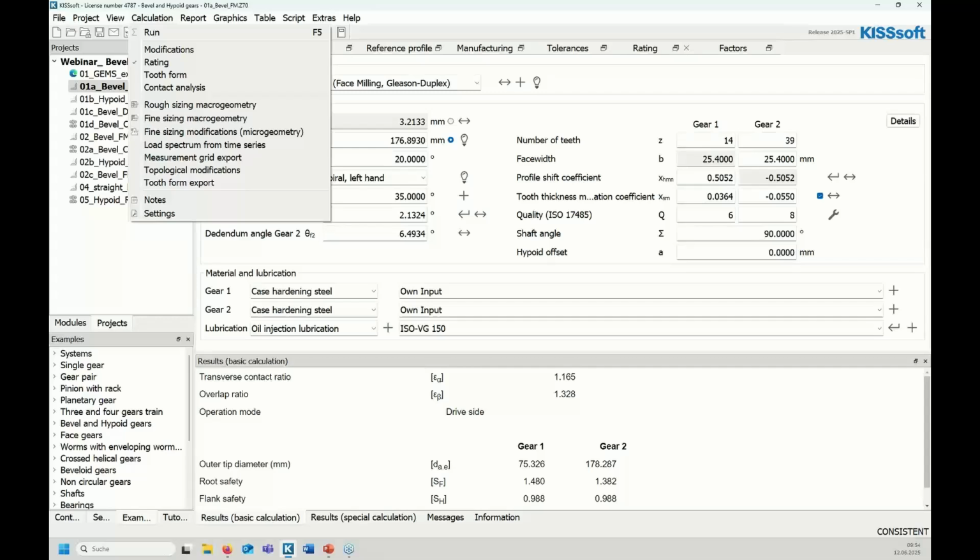The next question is, what is the recommended DIN accuracy class for spiral bevel gear? That's a good question, because this depends strongly on the selected hard finishing method. If you use lapping, lapping achieves DIN quality 8 to 9, to be honest. It depends on the hardening process.